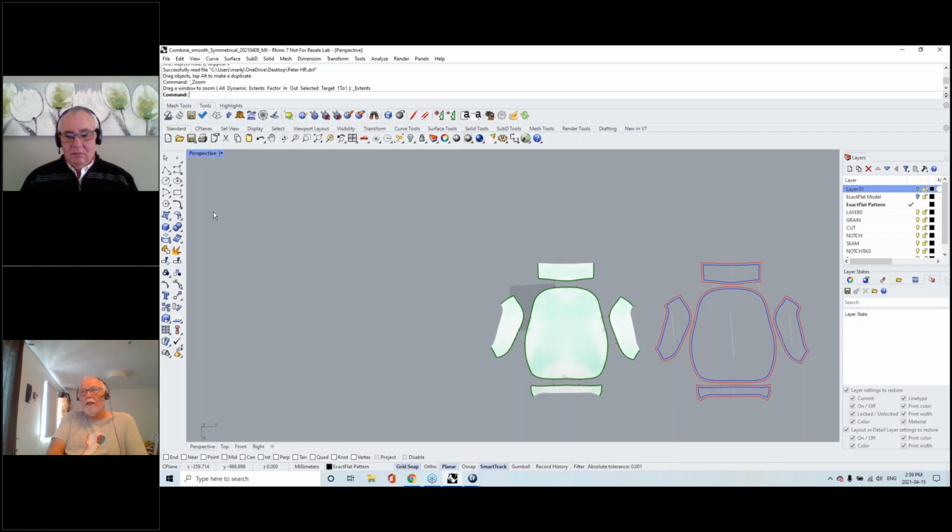The scanner can track by three things: targets alone, targets and unique geometry, or even targets, geometry, and texture, which is the scanning world's word for color picture. So we almost all the time track by targets and geometry.